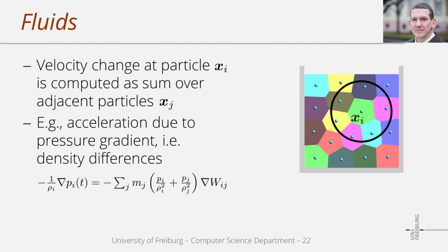Here on this slide, I'd like to discuss the question how to compute the forces from the Navier-Stokes equation. We have seen that we need to estimate the gradient of the pressure field at a particle, or we need to be able to compute the Laplacian of the velocity field at a particle for the viscosity force. In order to compute the particle forces, so-called discretization schemes are employed. And in terms of fluid forces, we often use a concept that is called smoothed particle hydrodynamics, SPH.